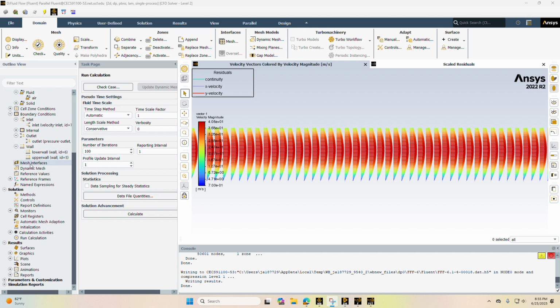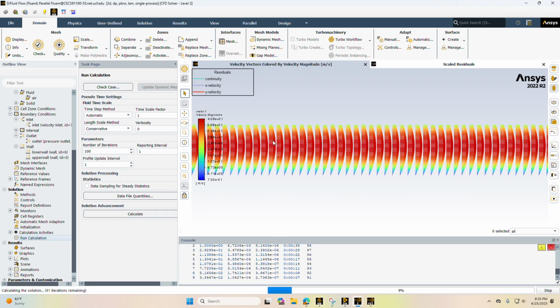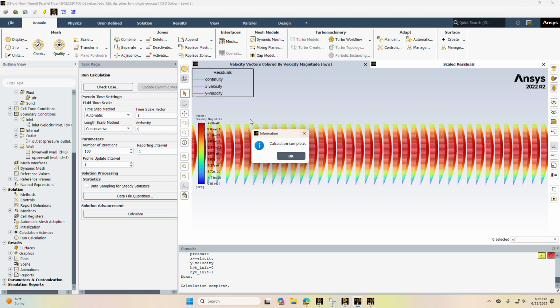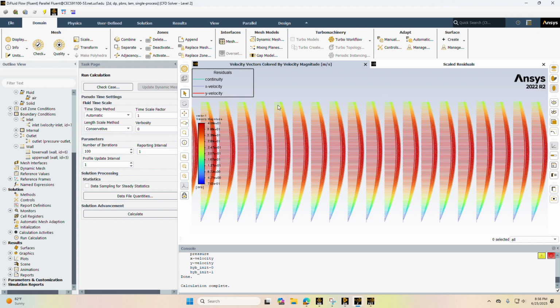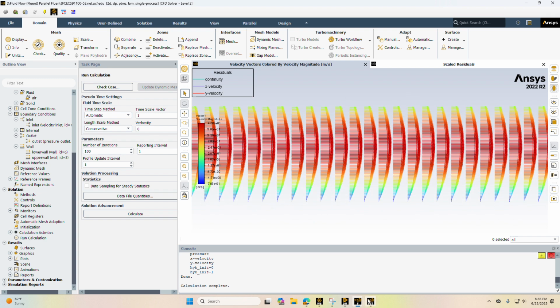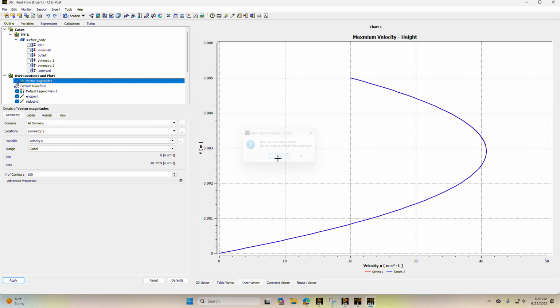And then we basically run it again after we change the velocities. Doing so will give us this graph. I had already run it, but it gives us this velocity. We should see the combination of the flows, where we have the Poiseuille inlet flow coming in this fashion towards the middle, and then we have the acceleration from the moving top wall. And so we end up getting a graph that looks like this, rather than that straight line. Here we see that the maximum velocity is around 0.003 millimeters, and the height a little lower.